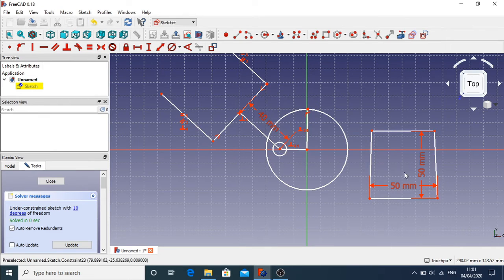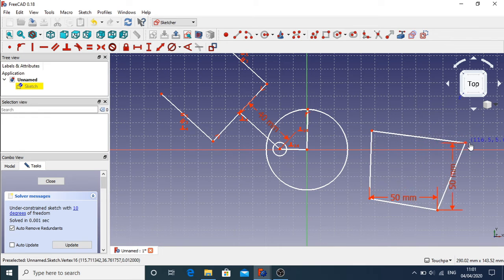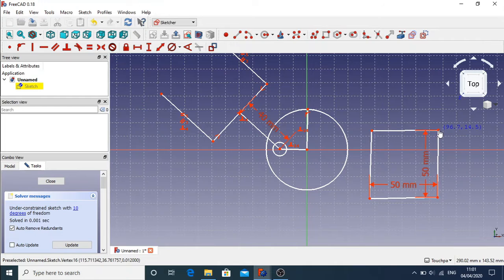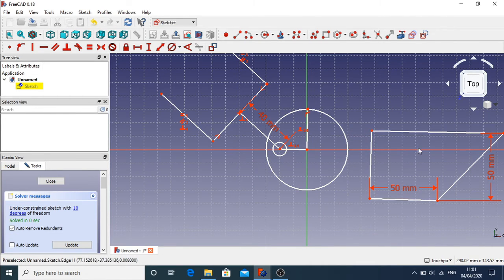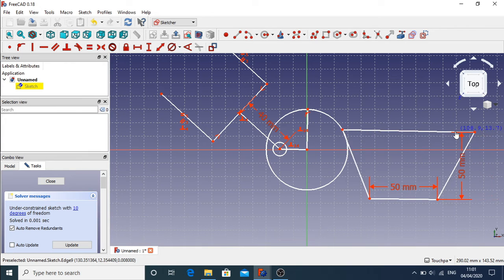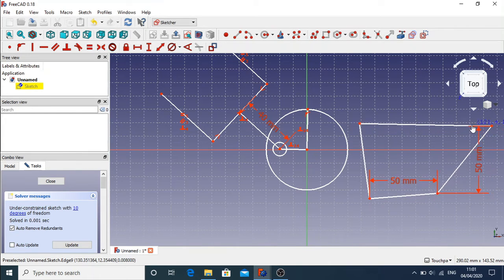So we fix the height and the width of that line, but what we've got to remember is that, although we fix the height of that line, if we take it off at an angle, you can see this line is longer. So height and length are only really suitable if you're constraining along the horizontal and vertical axis.